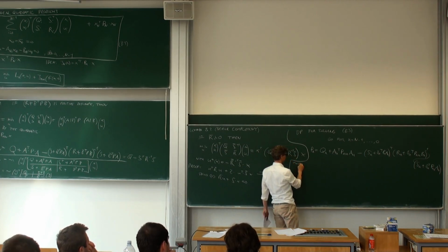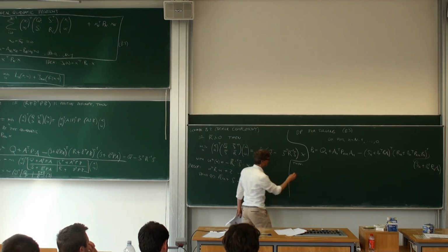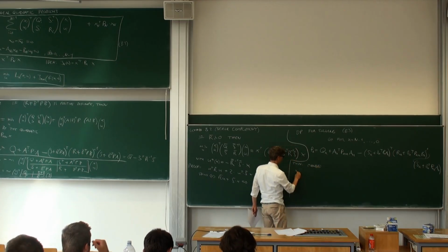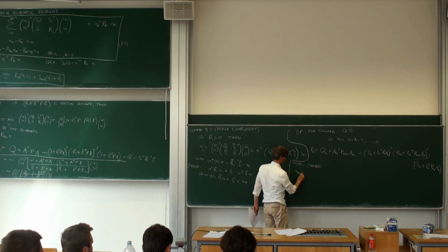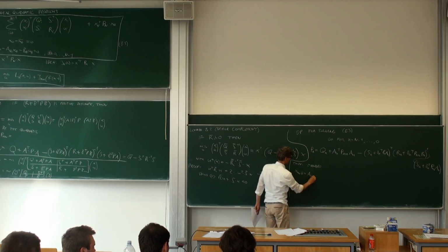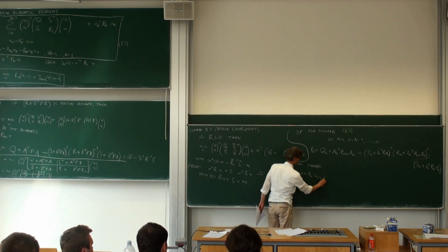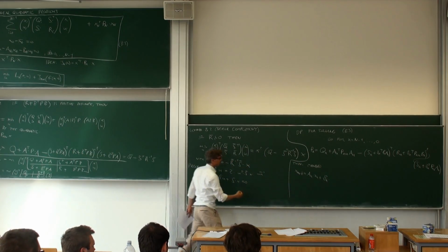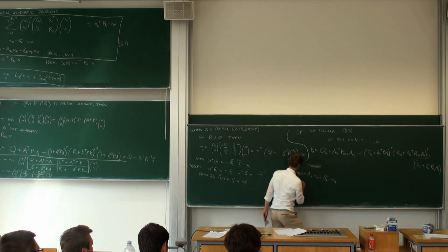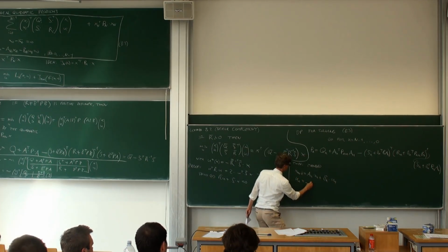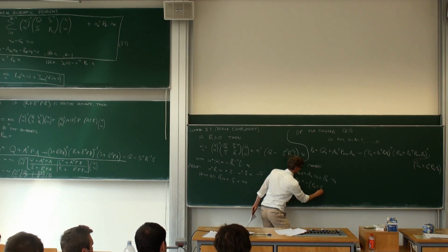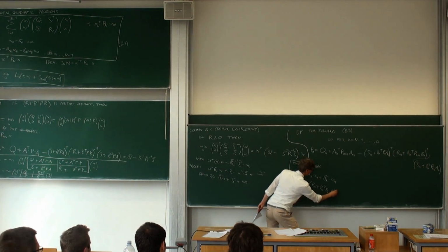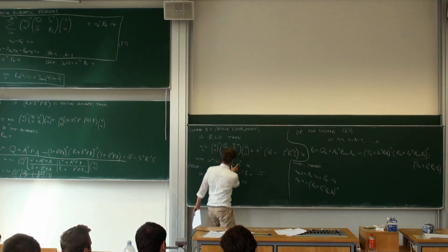And now, what do you do as the next thing? You make a forward recursion. And the forward recursion will be easy because x_{k+1} is given by A_k times x_k plus B_k times u_k, but u_k was just given by this formula here. Maybe I write it like that. u_k is given by minus R_k plus B_k transpose P_{k+1} B_k to the minus 1 times S bar.